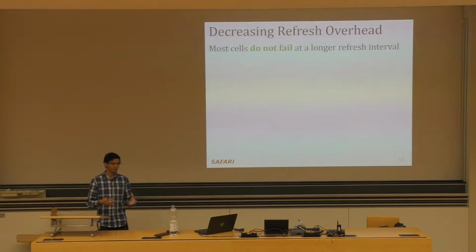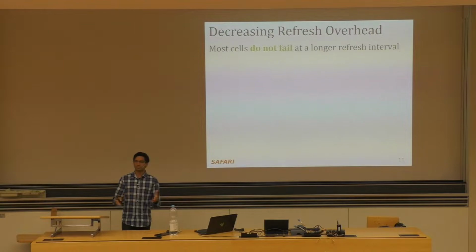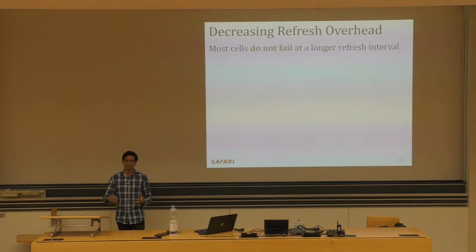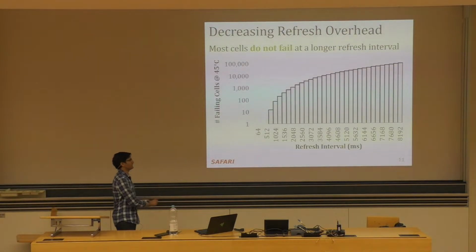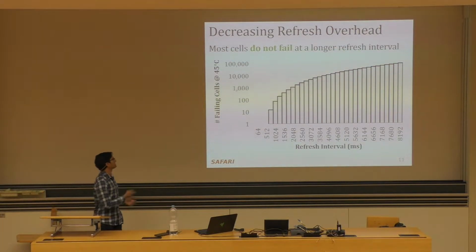It turns out that we can actually do this. Most cells actually don't need such a short refresh interval, and they actually won't fail if we extend the refresh interval a little bit. So here's some data that comes from our experimental analysis. On the y-axis, we show the number of failing cells in this device, and note that it's a log axis.